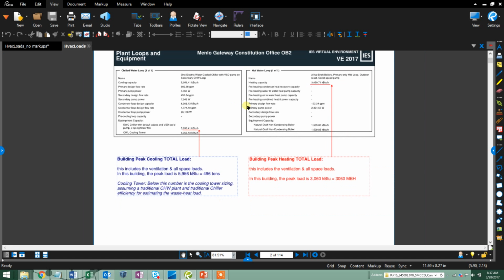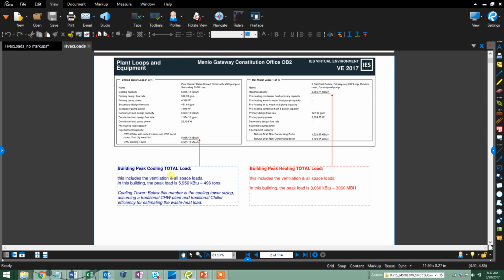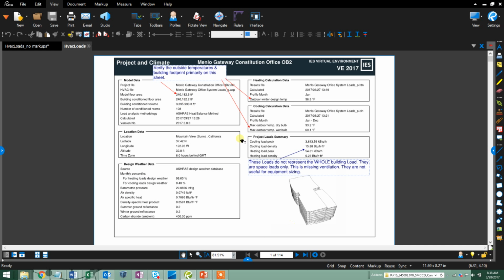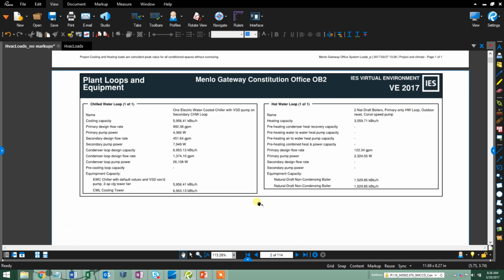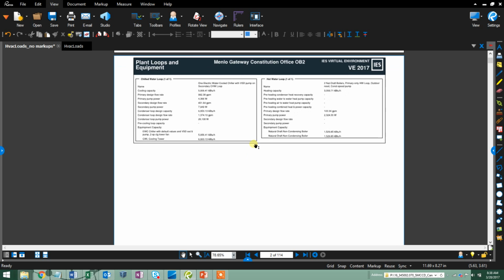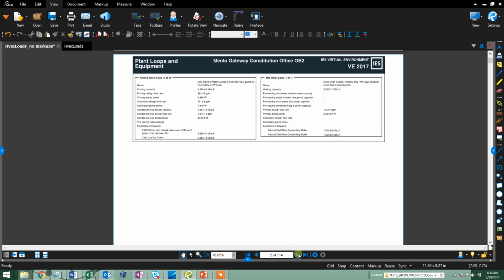So this report is really the best, right, for the building's total cooling, the building's total heating. You get a very quick sense of what's the tons, what's the heating load, and already you can take 500 tons, take the square footage from the model, and get a square foot per ton to sort of check against instincts. The next report I want to jump to is the systems report for the entire building's primary air handling unit, which in this building is a dedicated outside air system that serves fan coils.